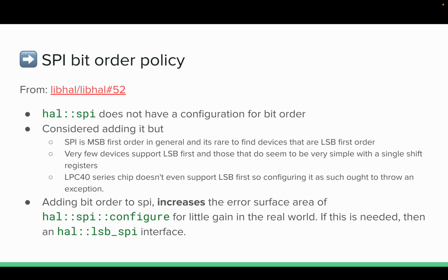All right, so now we have SPI bit order policy. HAL SPI, the interface, does not have a configuration for bit order. I never considered it, mostly because I've almost always seen the bit order for SPI be MSB. I was looking at some Linux HAL APIs as well as some other HAL abstractions, and I noticed that they had an LSB first flag. I was like, oh, that's interesting.